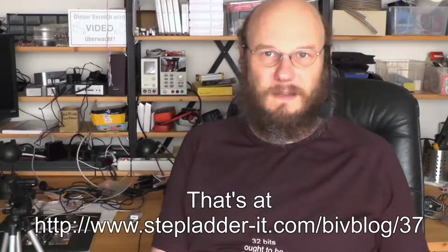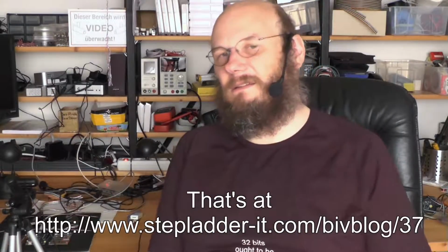If you want to use it, you have to compile it from source, and in episode 37 I've already provided you with a makefile that takes care of all the stuff, at least on a Raspbian. And well, command line options are a bit different, but other than that, yeah. The other problem there is, however, not all PIC microcontrollers are actually supported by that compiler, and the PIC14 family, which is named PIC16F whatever. Yeah, this is just to make things look more difficult than they actually are.